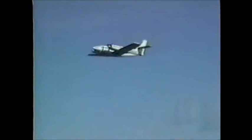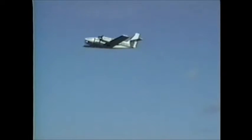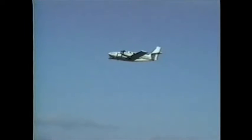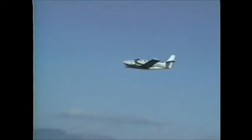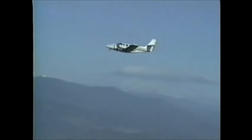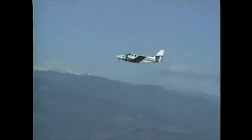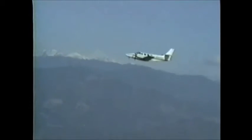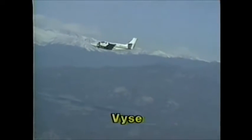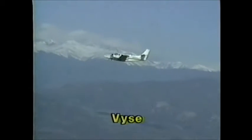However, if the engine fails while you're cruising above the single-engine service ceiling, you'll have to descend at VYSE to that ceiling. This is particularly significant if you're over high terrain. Obviously, your pre-flight planning should include reviewing areas of lower terrain and the locations of alternate airports. Remember, descending at VYSE gives you the slowest rate of descent and conserves altitude for the longest time.